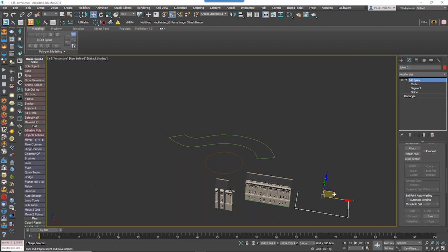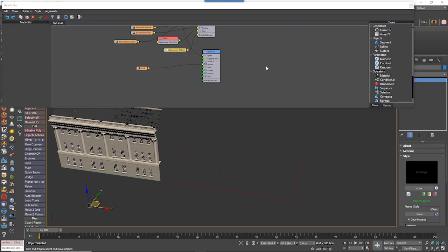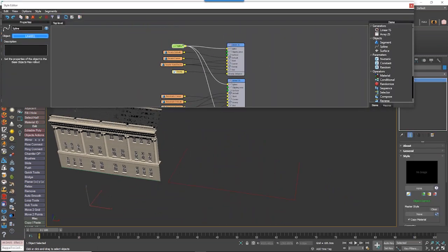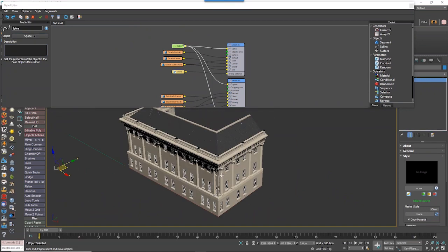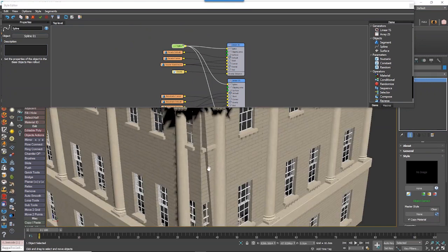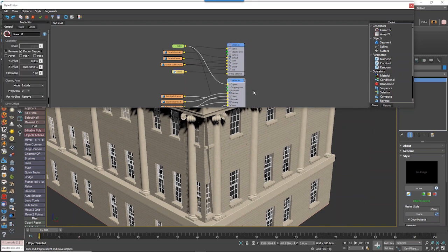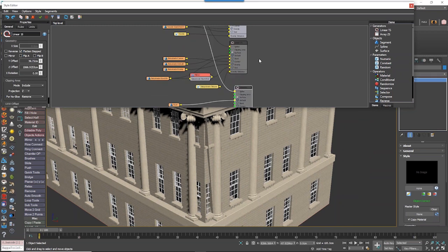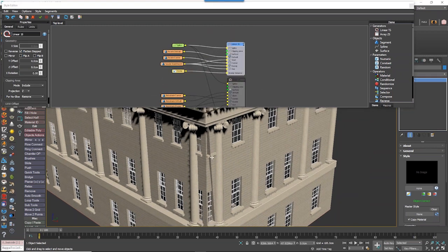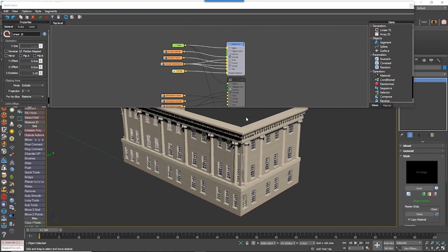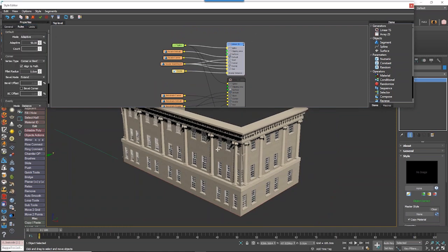And I get myself a pretty nifty little facade. Let's just double check the corners because I think they'll need some work. So let's bring a spline over here and just reassign this spline to this angled spline here. Yeah, there's some slightly weird stuff going on in the corners. So let me just turn these off. Basically, the corner geometry is being bent around the spline here, and I want it to be beveled. All the rules for the corners are controlled from the corner group in the rules tab. And I would want to, in this case, hit bevel corner, which bevels that corner there.